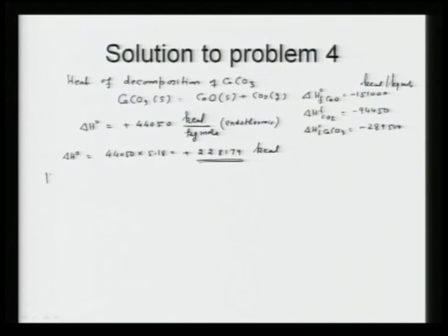Now, we have to calculate the heat content of pig iron. The temperature is given as 1700 Kelvin. So, the heat content in pig iron will consist of the sensible heat of elements, which probably all of you know. Do not forget to consider the heat of mixing. So, first I will consider the sensible heat of the elements.